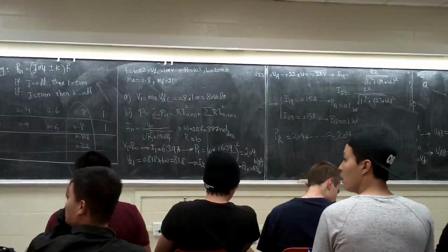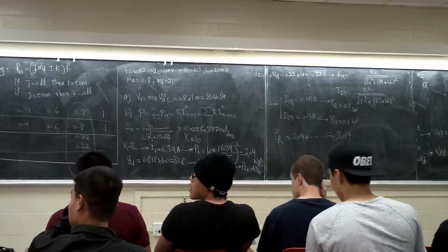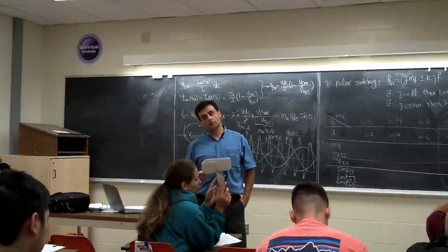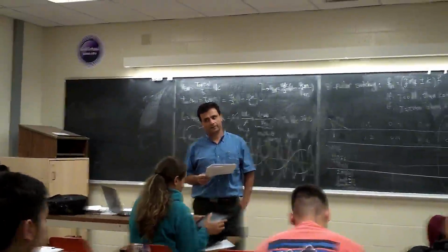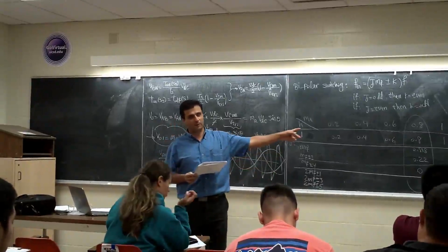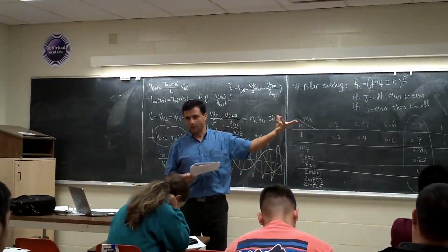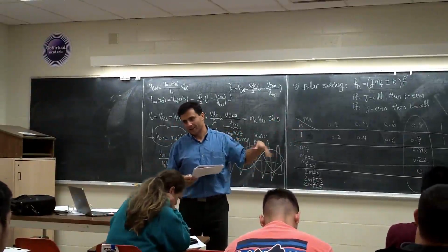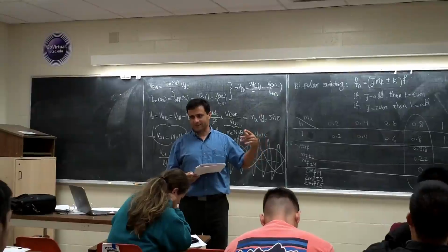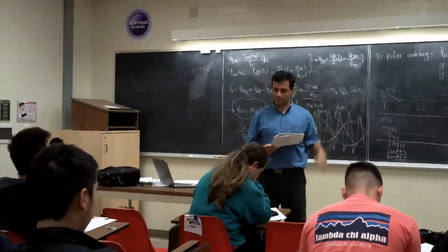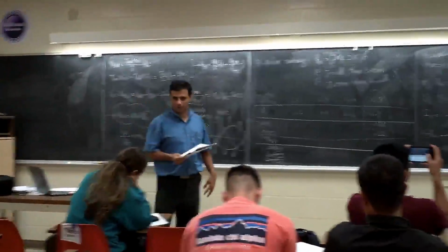How to make the voltage and current flow almost the same? For the voltage, you have to use the C filter. See why the current is looking better here? Because we have an L filter, right? The RL load has an L, there is no capacitor here. If you're going to clean up the voltage, you need to have a C filter. We'll get there.